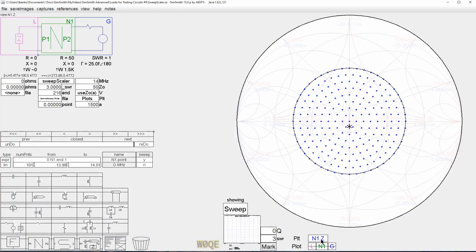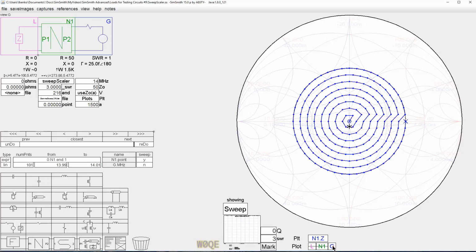If I plot this, but if I also turn this on, I see a path. So each one of these points now has a value. Notice that we're sweeping right now. I should have mentioned this earlier too, we're sweeping from 0 to component N1, the end value, in steps of 1. So that's why we see steps of 1 here going along.